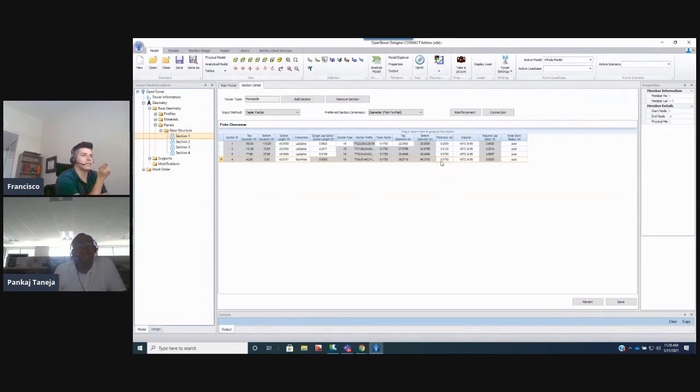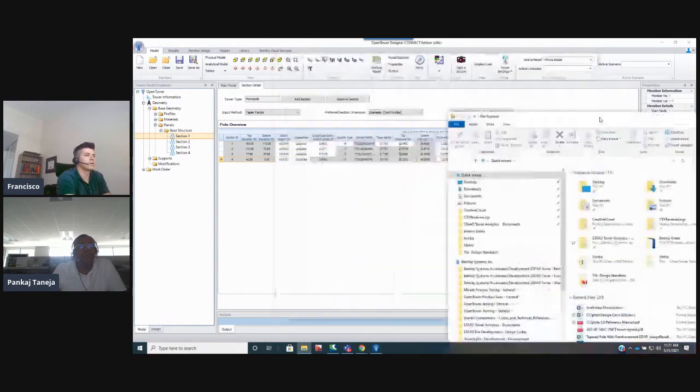Okay. Along those lines, I see that we have the inside bend radius, and it's auto calculated, it looks like, right? So we say yes, auto. Why do we say auto? That's a very good question. If we go back to our different design standards, we have TIA-222-F, TIA-222-G, and now TIA-222-H. In F and G, we assume that the bend radius of the plate is almost four times the thickness. But TIA-222-H, let me bring that one too.